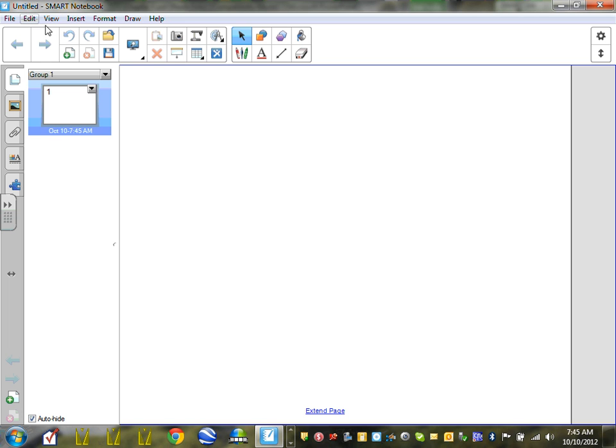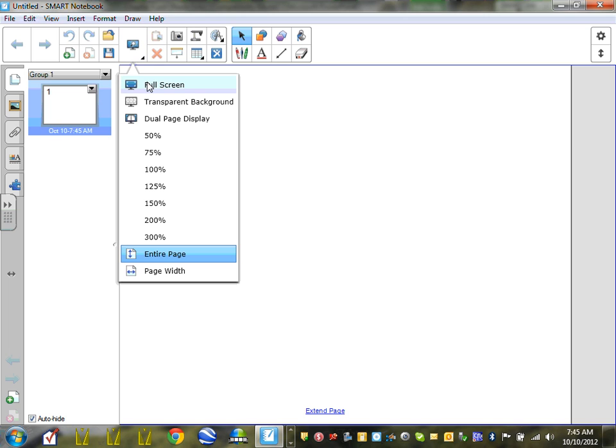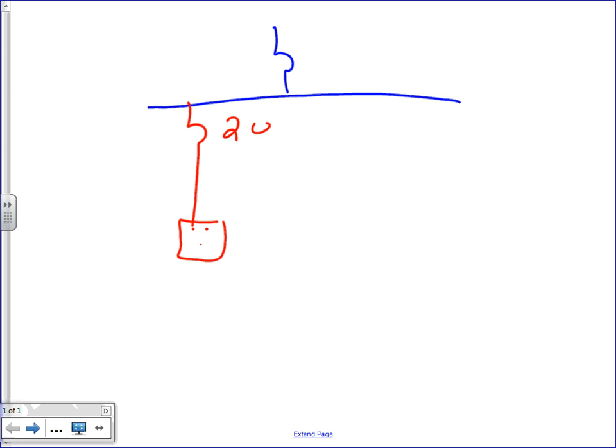I'm just going to draw a branch circuit and show you the most important thing in this branch circuit that you're going to be encountering. So here's your branch circuit. Let's put the 3 types of branch circuits that are dear to my heart and dear to yours. Here's my panel, and I'm going to show branch circuit number 1. Here's my 20 amp branch circuit. Right out of this, I have receptacles. So this will be my receptacle branch circuit, right?